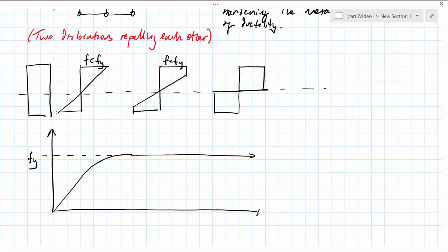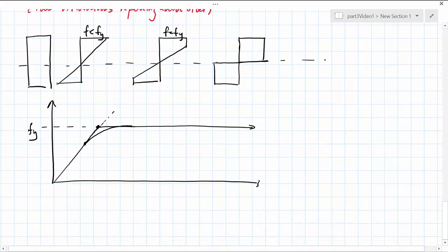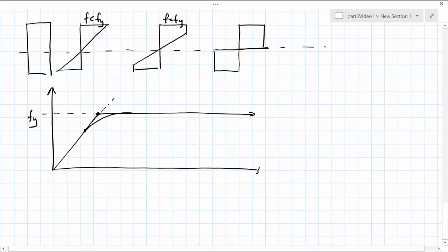To simplify things further, in plastic analysis, we ignore the curved nonlinear section between first yield of the outer fibers and full plasticity, and we assume the stress-strain curve becomes horizontal immediately at yield. This is sometimes simplified further, where we assume what we call rigid plastic behavior, where the cross-section is immediately fully yielded.